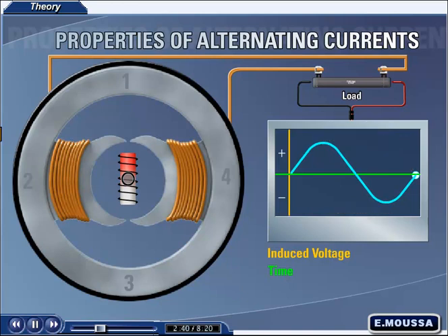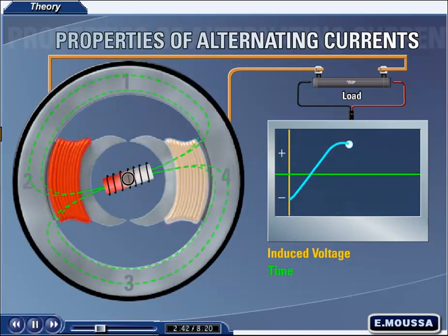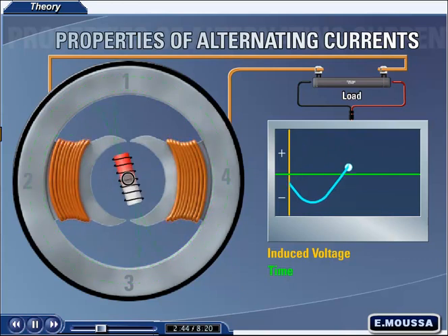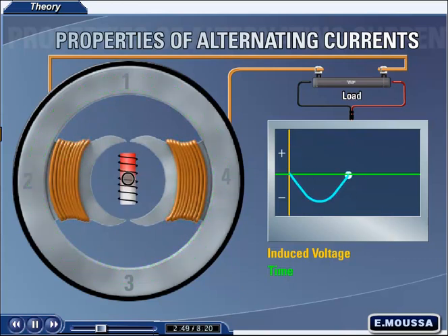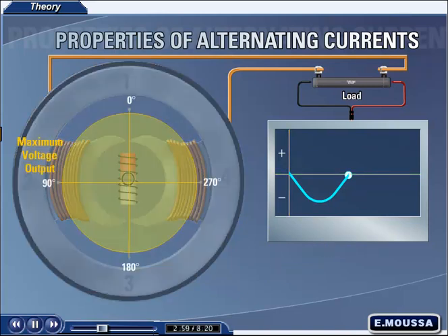One rotation of the exciter through 360 degrees produces one cycle of voltage that alternates polarity and hence current flow. This is referred to as alternating current, which is abbreviated as AC. We can now determine the output voltage at any given point in time along the sine wave by using the following process. To better understand this method, the voltage magnitude at a specific time of the sine wave will be plotted on this XY graph.